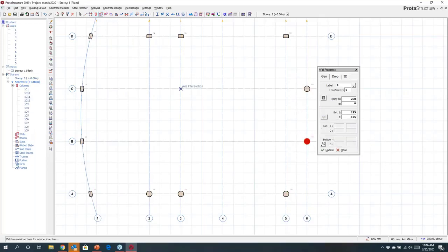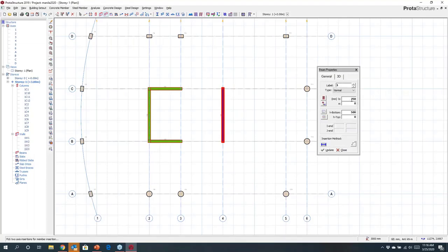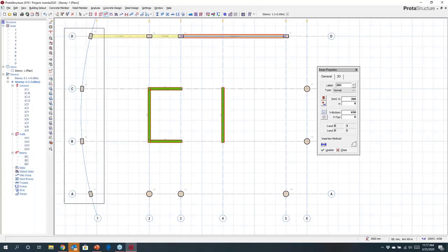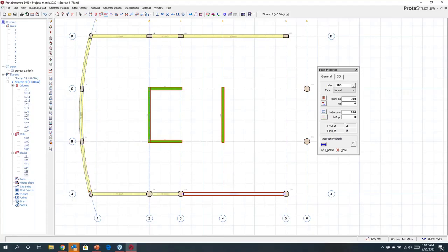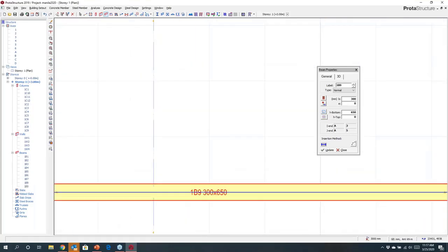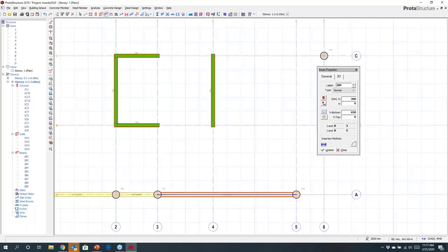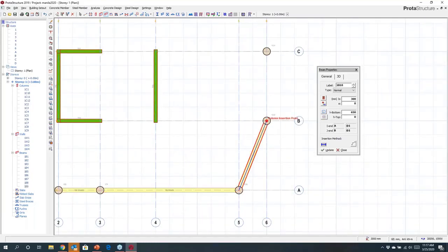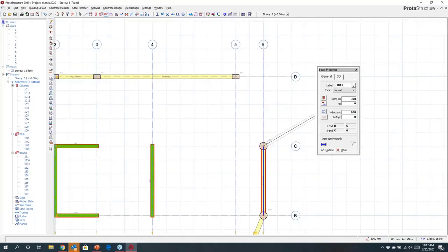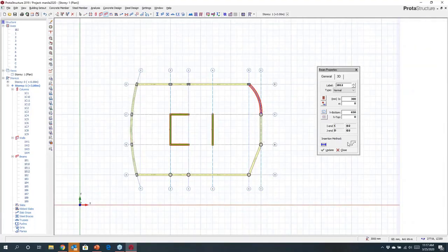Now I'm going to work with some core walls as well, and we can just place a core wall within the frame, okay, and draw some walls. Similarly with beams, you can place your beams here, and you can key in some properties here, okay, and you can then just come and box around to create. Now the interesting thing with this process is that as I'm going, and I'll just zoom in to show you, we're automatically labeling everything here. So everything's labeled and set out and you might just see or start to realize that this is starting to look a little bit like a key plan. So as I'm going around and developing this model, you can see that we're creating an arrangement here.